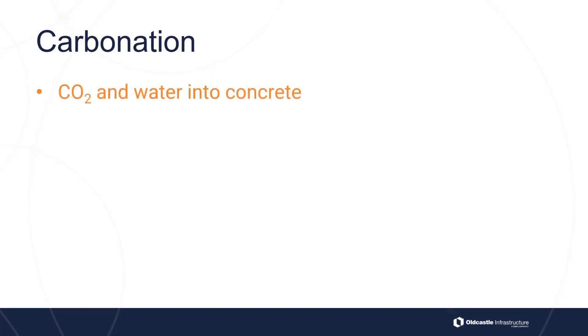carbonation is a chemical reaction between the carbon dioxide in the air and the calcium hydroxide and hydrated calcium silicate in the concrete. Basically, the carbon dioxide penetrates the concrete surface and dissolves in the pore water, which forms carbonic acid. The carbonic acid that forms in the concrete's pores reacts with calcium hydroxide in the cement, which is a desirable product of cement hydration because it inherently strengthens the concrete mix, and it produces calcium carbonate.